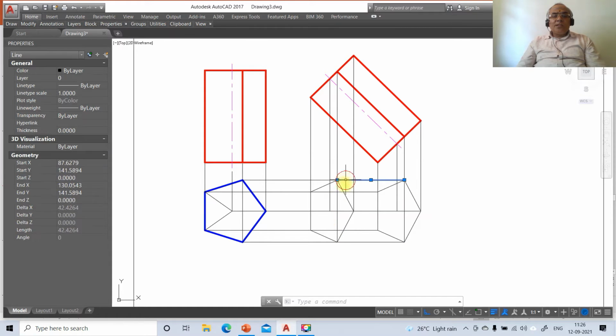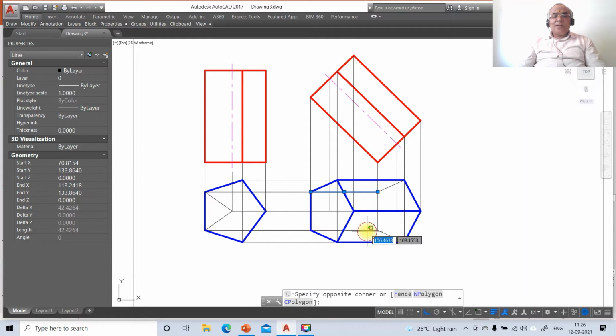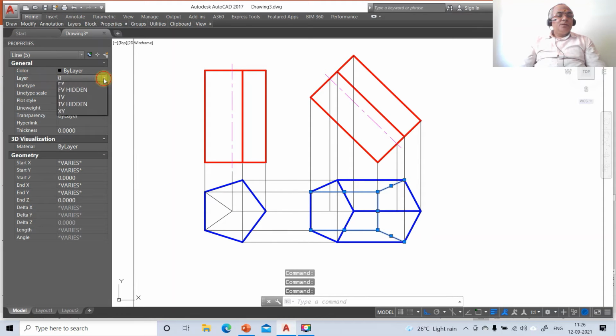Now we have all the exterior edges of the boundaries of the solids visible. Then we have the surface nearer to the observer visible. So naturally this line and this line become visible. Then go to line, take top view now. Now once you have this, this line and this line, two visible edges can never cross. So obviously these edges will also become top view hidden, and you make that as 15.